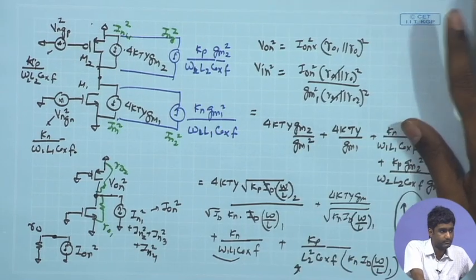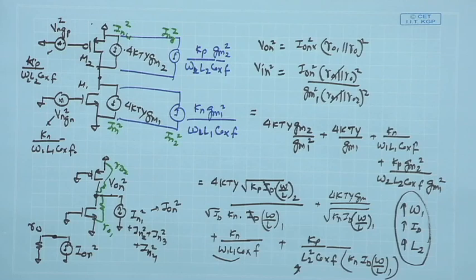Proceed. 1 upon F noise is due to trapping and releasing of electrons, but for PMOS, the gate voltage is not changing for active... No, but continuously there is always trapping and detrapping, so it's not only signal dependent. Randomly, under equilibrium, you have trapping and detrapping going on. When you apply the gate signal, it changes that trapping and detrapping process. But when you have two opposing phenomena going on, it reaches an equilibrium where the trapping and detrapping are equal in magnitude. That only means that the mean value of the noise that is produced is 0.